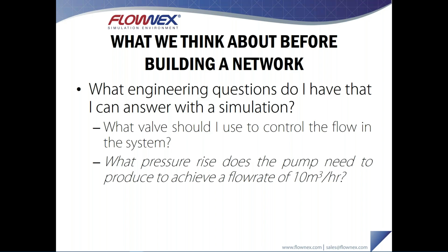We want to have a pressurized vessel with a level in it, and then some spray nozzles at the top, which can allow this warm water to be sprayed over our material and ultimately wash it. So we're going to have a system with a tank, a valve to control the level inside of the tank, and a pump to recirculate the fluid so that we can spray it down onto the material. And we basically want to size some of the components in here.